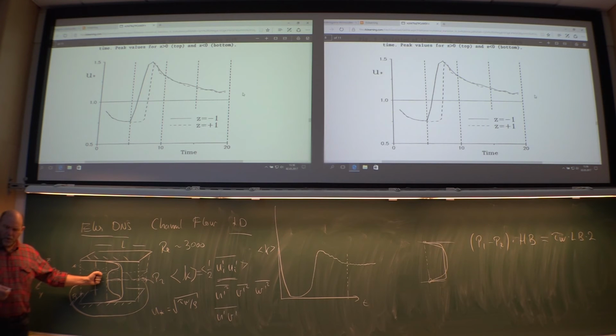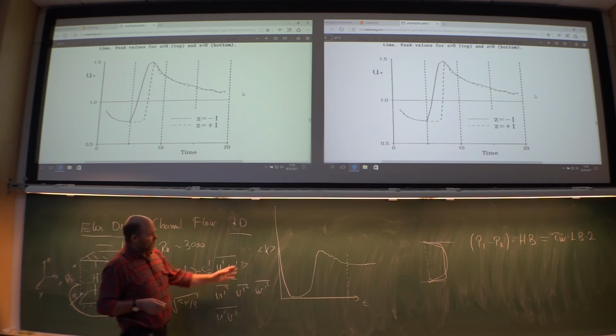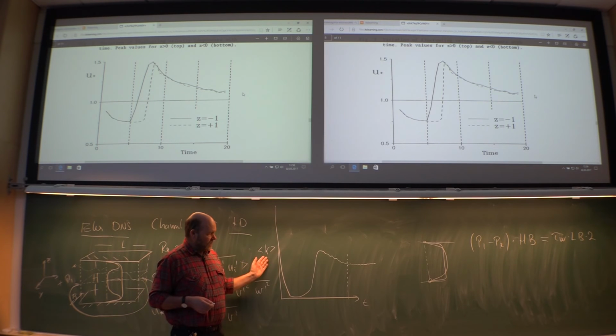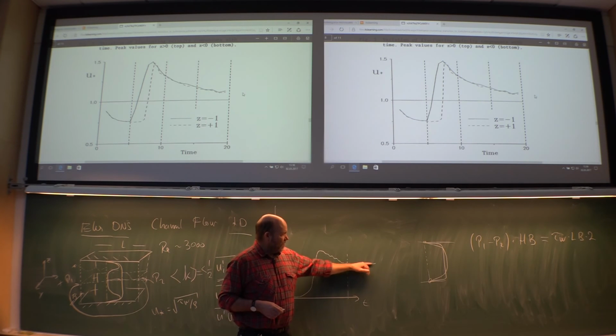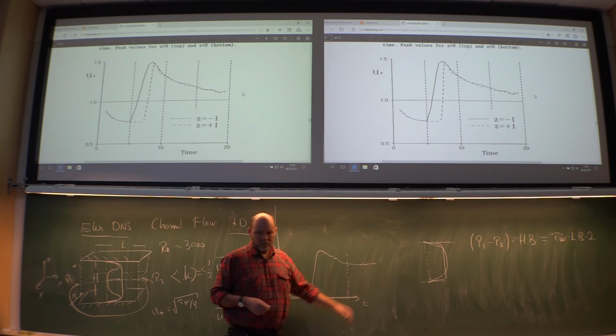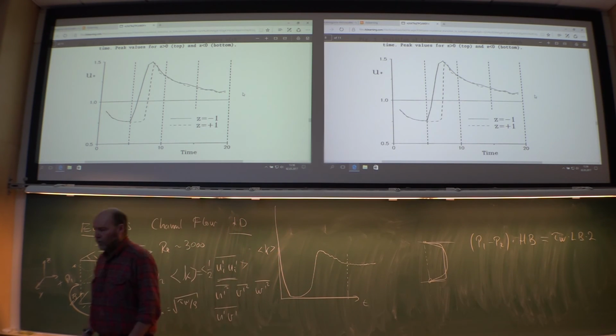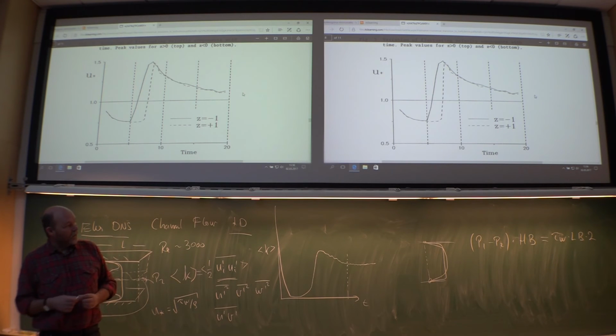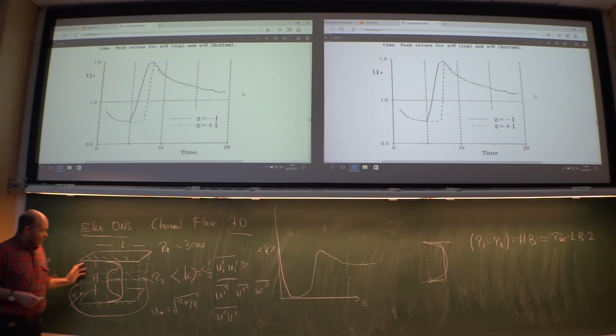When do you know that you have a solution? This was actually a very good monitor, the volume averaged turbulent kinetic energy. When it was leveling off, then okay, now I'm fairly safe. This force balance was another monitor I could use, a control volume analysis for the entire domain.